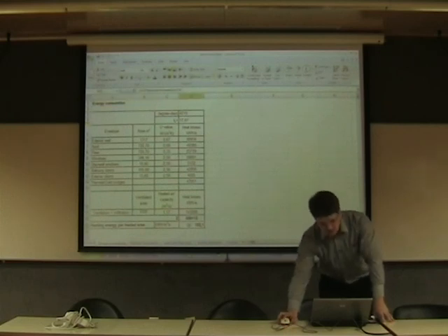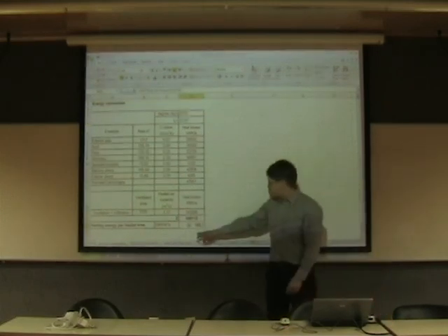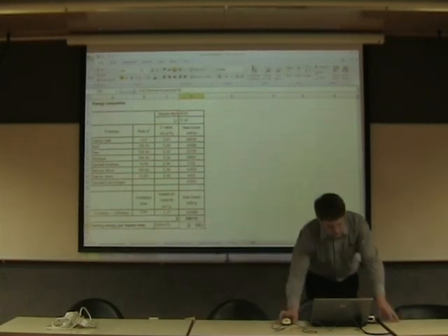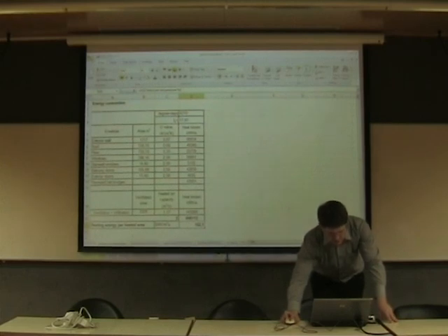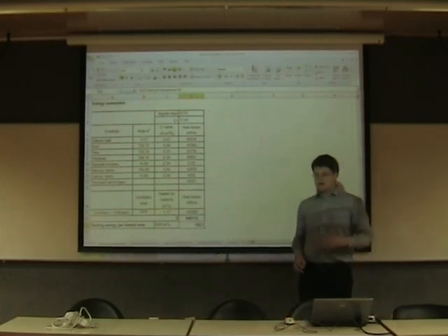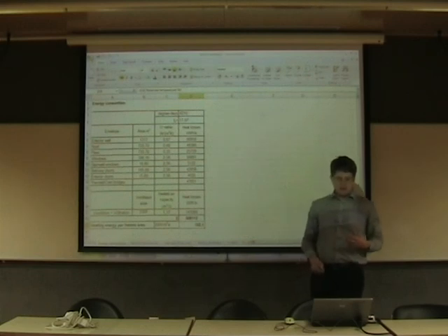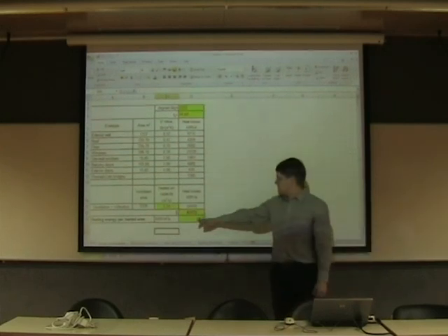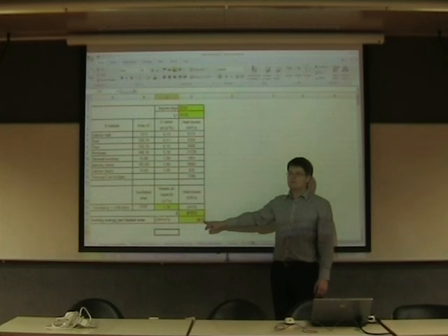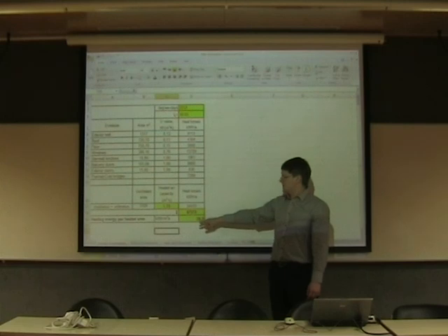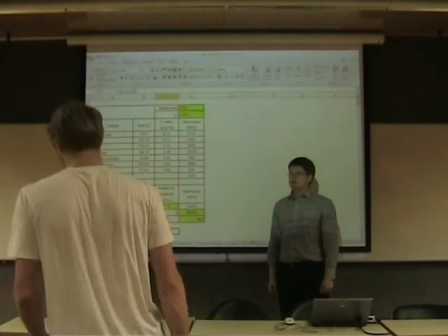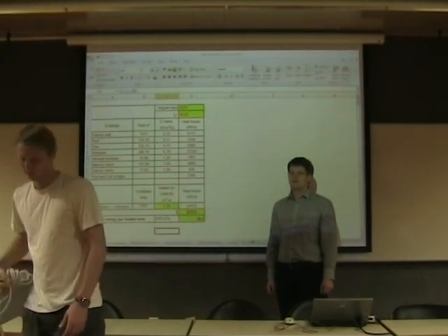The heating energy need was 152 before renovation, and when we change the U values and also recover heat from exhaust air, then it can be 26.3. But I think in the Estonian case, it's very hard to achieve a better value. But thank you, and that was all that I wanted to say.